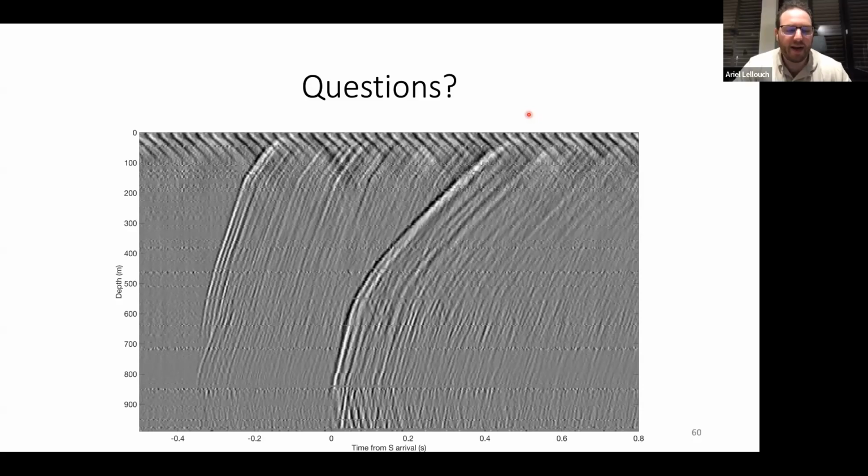Yeah, actually, it's a very good point, and I had to make some assumptions during this talk. I didn't want to get into the details. The problem is that because it looks at phase change of light, basically, if you have too much strain, you're going to go past 2 pi, and you're basically going to lose phase. And therefore, you're absolutely right. Every interrogator has a limit, and depending on its specific setup, you can sometimes change that limit. But if you're going to see a huge event in terms of strain with a standard acquisition like this, you're going to lose the phase.